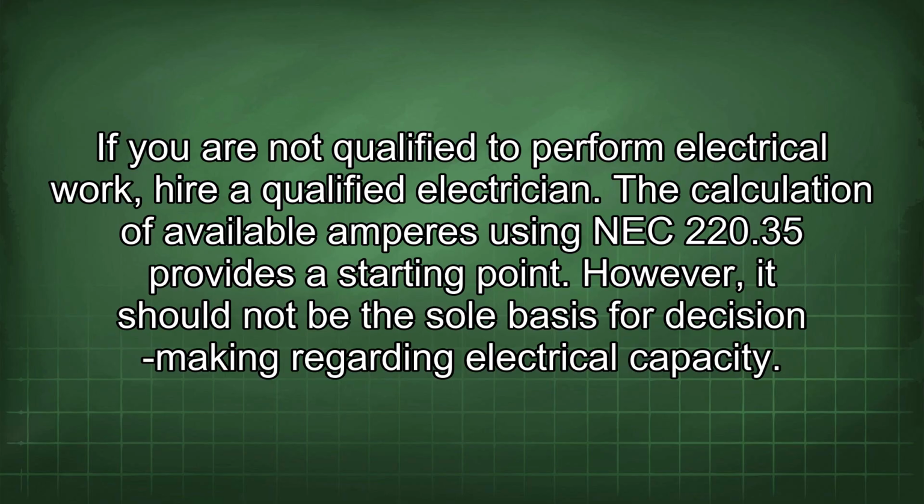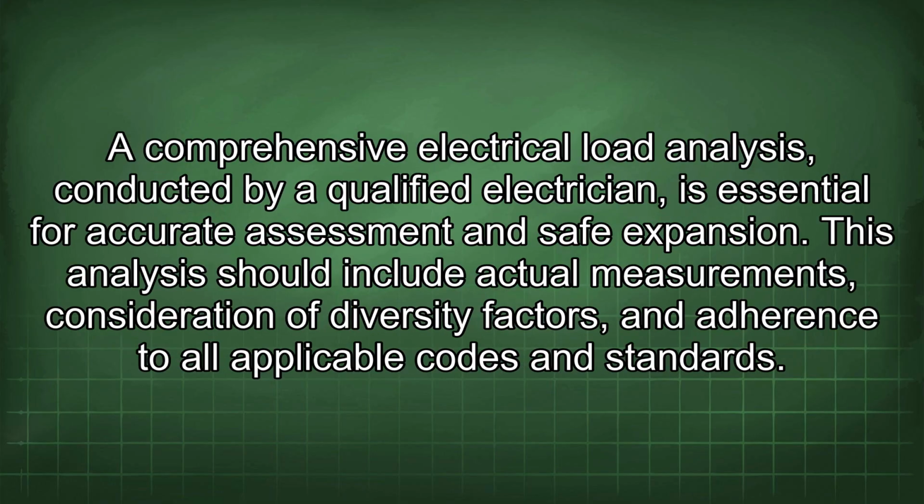The calculation of available amperes using NEC 220.35 provides a starting point. However, it should not be the sole basis for decision-making regarding electrical capacity. A comprehensive electrical load analysis conducted by a qualified electrician is essential for accurate assessment and safe expansion. This analysis should include actual measurements, consideration of diversity factors, and adherence to all applicable codes and standards.